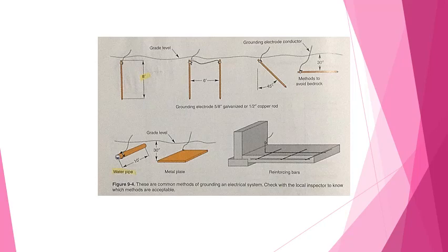Should overcurrent accidentally reach the system, it will be drained off harmlessly into the ground before it can damage any part of the system. The grounded conductor should never have its continuity interrupted by switches, fuses, or circuit breakers. This would cancel its value as a path to ground. Devices that interrupt the circuits can be used only on hot wires, ungrounded conductors.